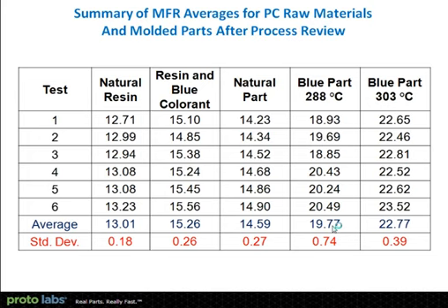Now that's still acceptable, but the problem we ran into is, and this is kind of ironic, once the material started to be dried properly, the viscosity went up. This is also something you'll see. Viscosity goes up as the moisture content goes down. So the molder started having trouble filling the parts. So they had to raise the temperature of the material in order to compensate for that increase in viscosity that resulted from the lower moisture content.